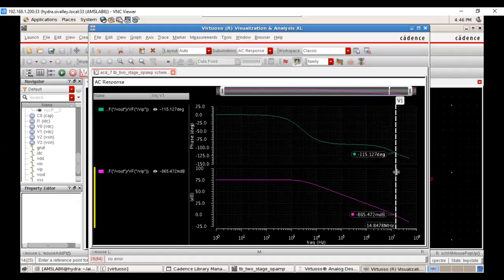Okay. Something is wrong. So did we make any mistake while entering the values? That we don't know. Anyways, we are just putting the exact numbers of what we calculated. We are able to get it. Okay. So 180 minus 113 is the phase margin, and zero crossover frequency is 13.6 megahertz. We have designed it for 10 megahertz, right? So that is also in good range. And we have designed for like 2000 gain, right?